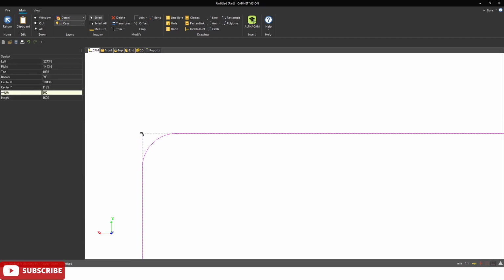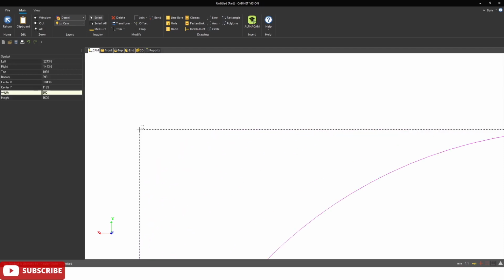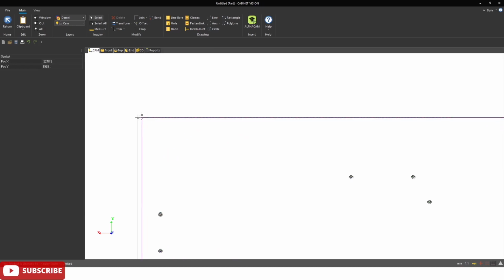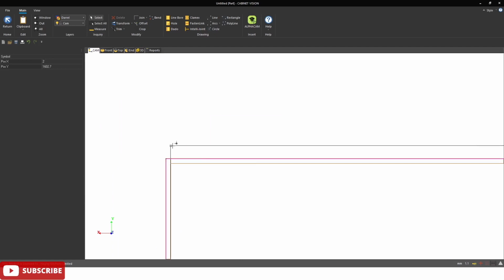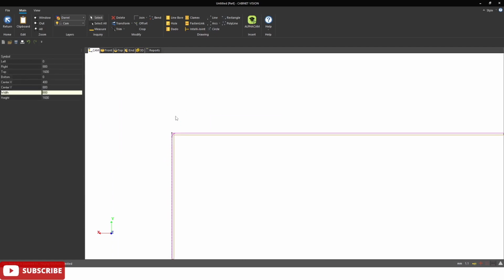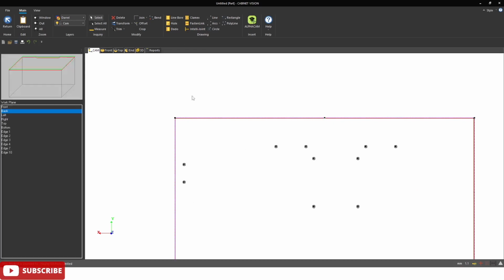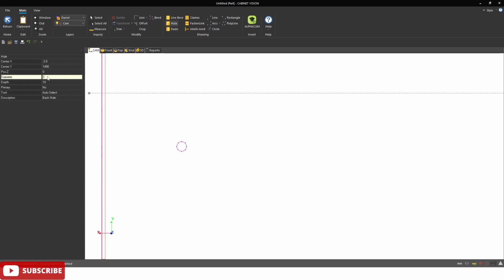So when I add it on, if I can get that, okay, if I can add it on, I'll show you once. I've done all the drillings. So now we're going to add, first off, these two holes. We're going to do a couple of holes. I'll show you how to do the holes. So it's 3mm diameter and it's going 10mm deep in auto select tool.